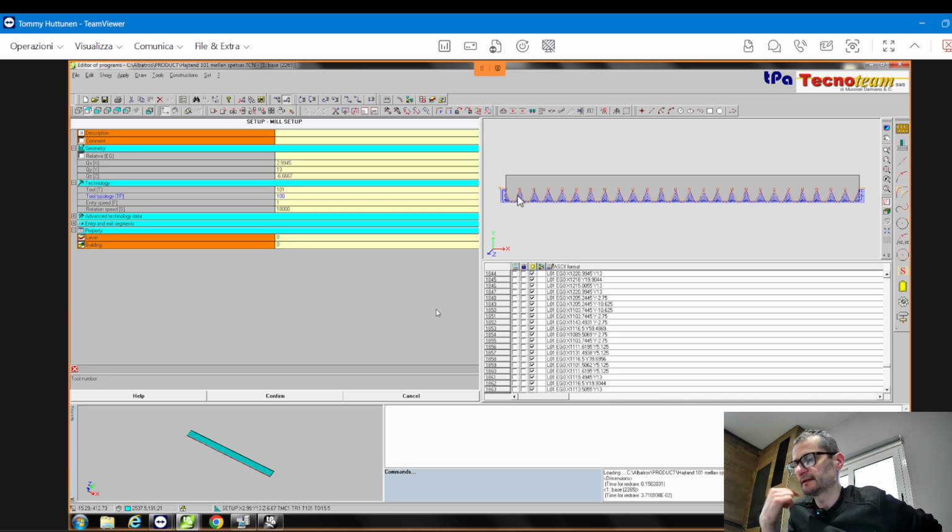Start the cycle. What happens when I put this in the machine? What happens when I don't see very well what is happening, so I'm in a panic? This part depends on you, but you must practice with the machine. Also start to make some bores. Maybe you can start from side number 1, using the boring bit of the machine.